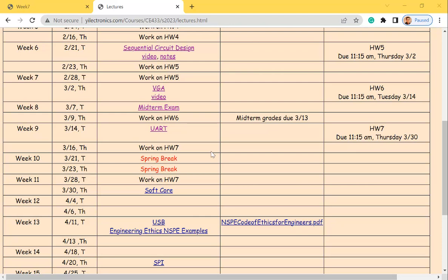So what about we use one of the GPIO pins available on the FPGA board and assign them as the RX and TX pins for the FPGA. Since it's all flexible, you are doing ASIC design. You can design whichever pin to be used as RX and TX for the chip, right? So if you have that on the GPIO pins as RX and TX, how do you verify the logic from there? What do you think? What are the ways to do it? It's a standard communication protocol. If it's UART, it's going to be UART everywhere. It's the same logic.